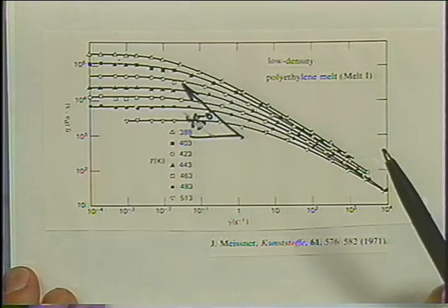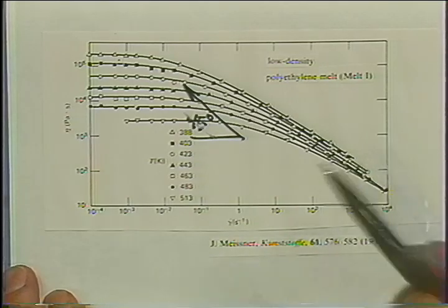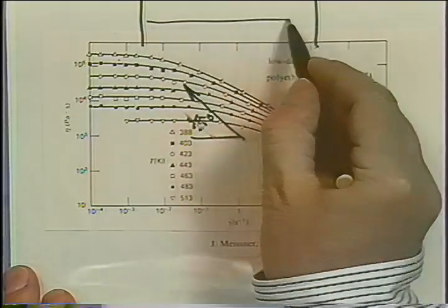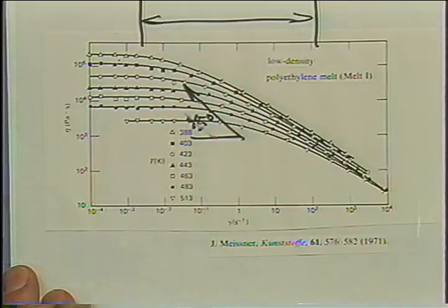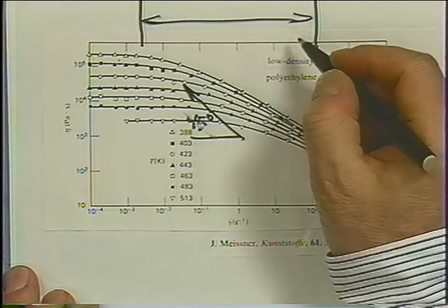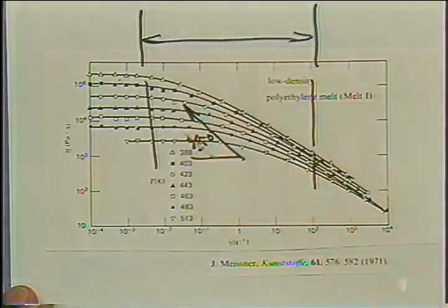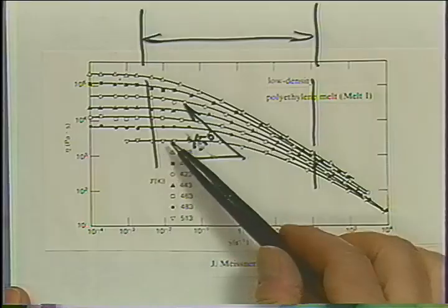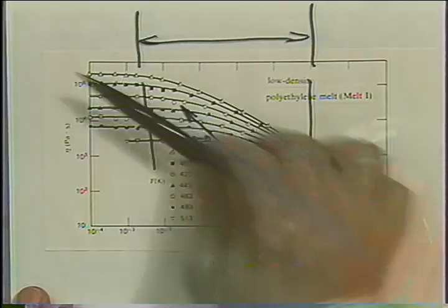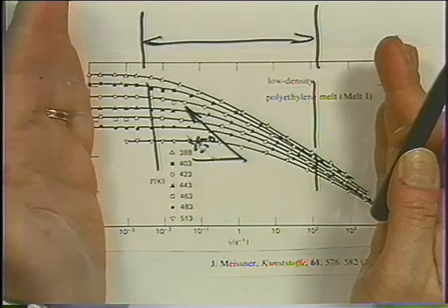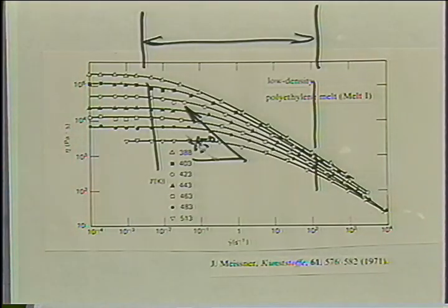From an experimental point of view, that's quite an opportunity, because our rheometer will most likely have just a window, maybe a frequency window or a shear rate window as such. So we only would get data in this fashion. But now if we have data at different temperatures, we can shift them out of this window and our overall experimental window is extended by this so-called time-temperature superposition.